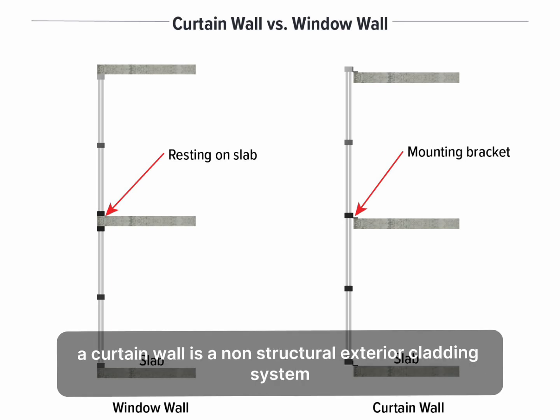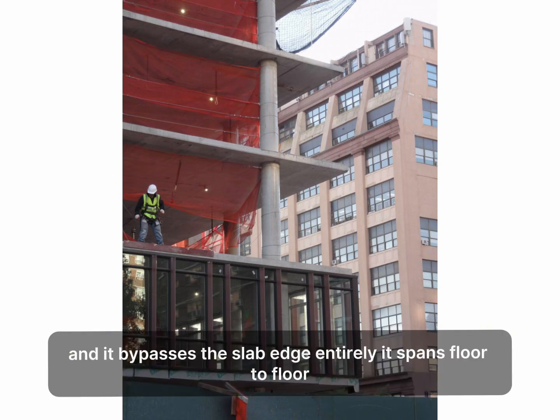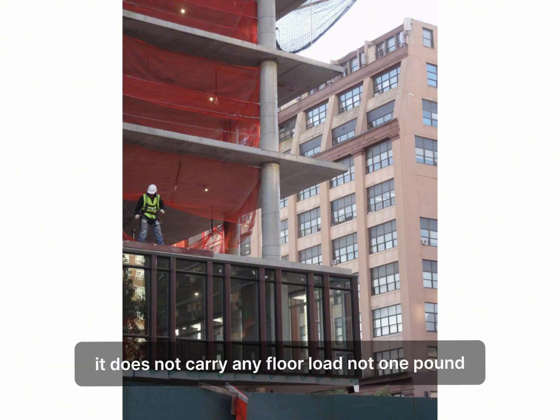A curtain wall is a non-structural exterior cladding system. It hangs off the building's primary structure, usually steel or concrete, and it bypasses the slab edge entirely. It spans floor to floor. It carries its own dead load plus wind load. It transfers those loads back to the structure at the anchor points. It does not carry any floor load, not 1 pound.